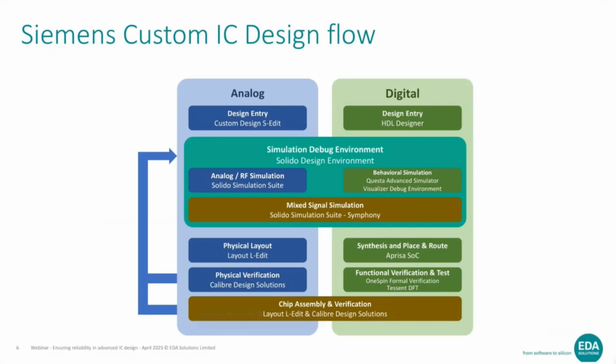On the analog design side of things, the flow begins with S-Edit, which is part of the custom IC package, while on the digital development side of things, we leverage the HDL Designer tool. Simulation and debug are unified through the Solido design environment, which offers an AI-powered flow, variation analysis, and advanced waveform processing capabilities using the Solido waveform viewer. The Solido simulation suite takes care of individual analog and digital simulations with tools like FastSPICE and Questa, and Symphony provides a robust mixed signal simulation for seamless integration of both analog and digital domains.